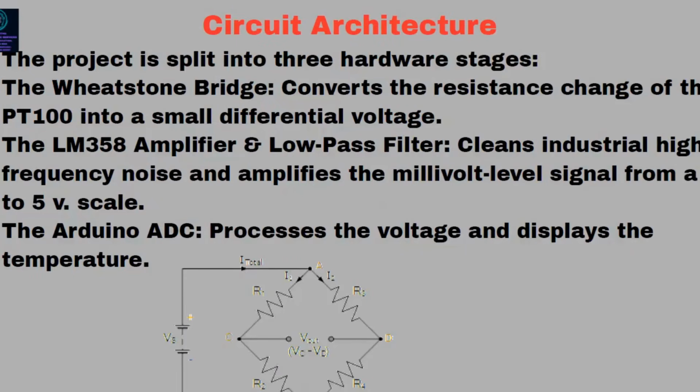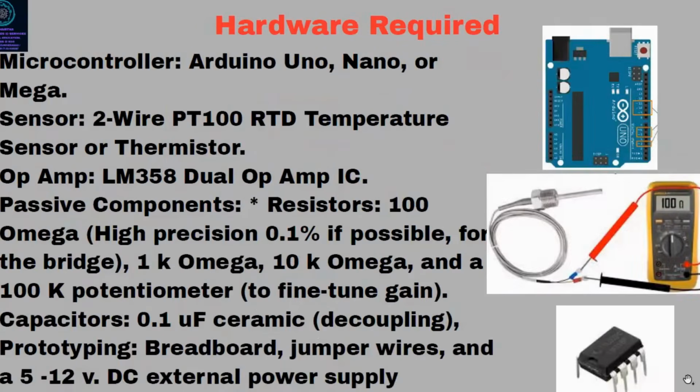Third is the Arduino ADC, where we use a microcontroller. The microcontroller board is an Arduino board. We use its analog to digital converter to process the voltage and display the temperature. So these are the three stages we will be going through. Right, the Wheatstone bridge, I just told you the reason. The hardware component required is a microcontroller; any microcontroller you can take.